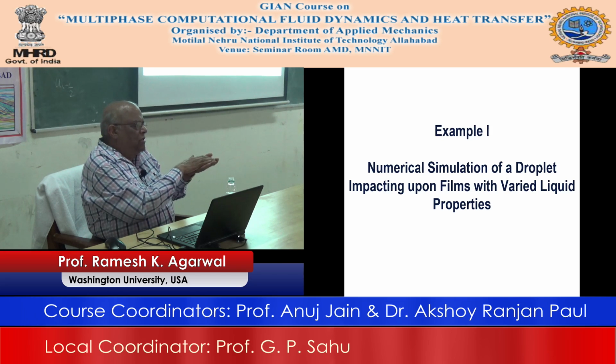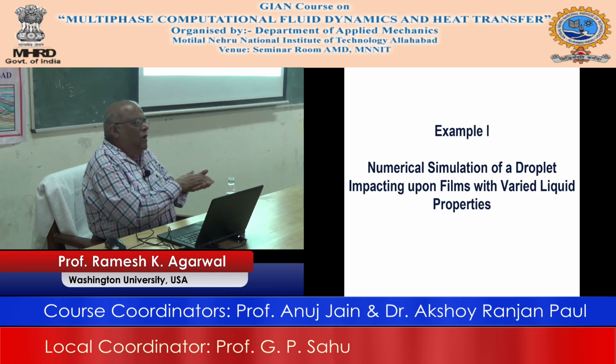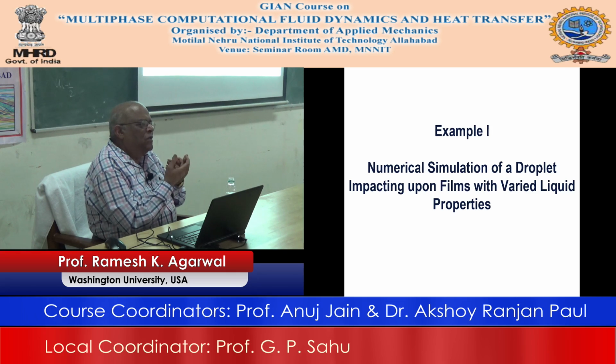So here the problem is that we have a liquid droplet, which is spherical, and it is hitting a film, and in that film we will change the viscosity of the material to see what is the effect of the hitting of the droplet and how the shape of the droplet changes and how the viscosity may play a role, and primarily that is manifested by the Reynolds number, and the other effect of the surface tension is manifested by the Weber number.